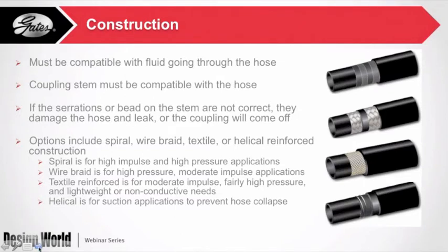You're going to have some more deformation of the wire because it's not so much steel there. You're actually going to deform some of that wire, bite the wire is what we call it, and that's going to give you your coupling retention. So you're going to see that on everything from hydraulics to water blast hose, or some of your industrial media blasting type hoses and the like. Again, extremely high pressure, so it's something you're going to have to be careful of, but couplings will have to be made specifically for that type of hose.